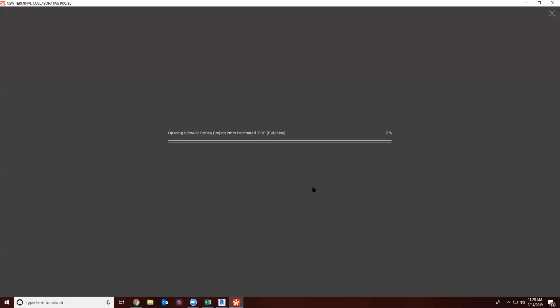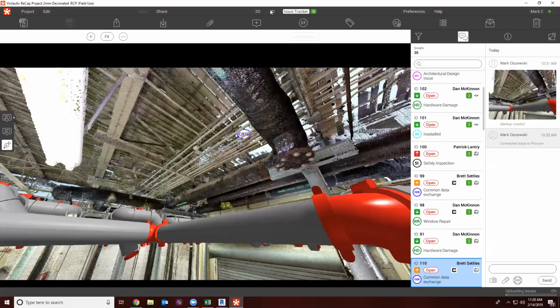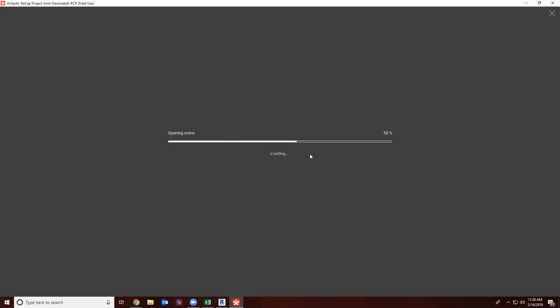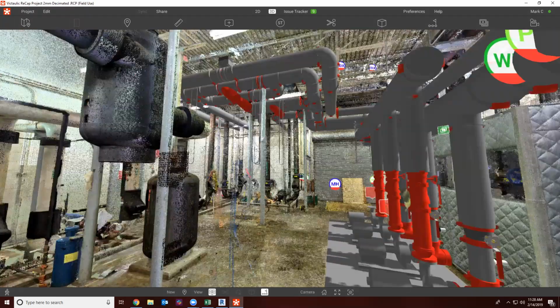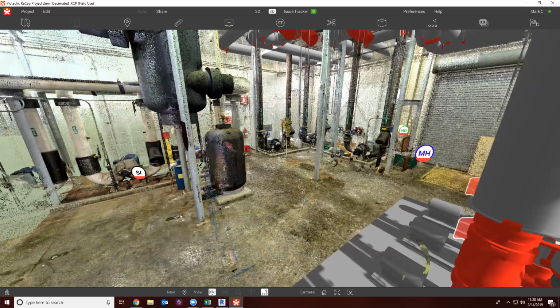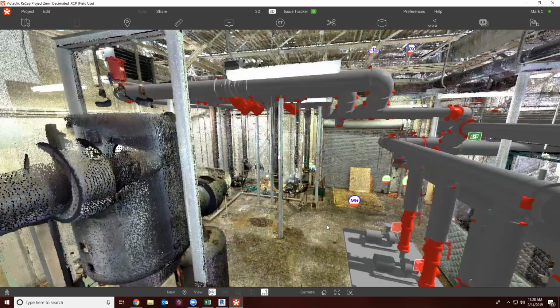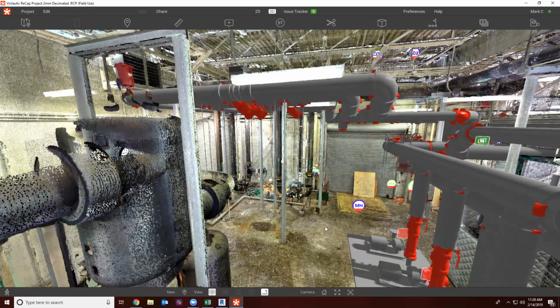Yeah, because really you could treat it as a coordination issue that needs to be resolved, which really just means you need to update the BIM to meet the as-built, and it would only be in that condition where that change that you identified actually created an issue and needed a design change that it would be elevated to an RFI. Absolutely. Yeah, same workflow in a different phase. Yeah, so taking this full circle.